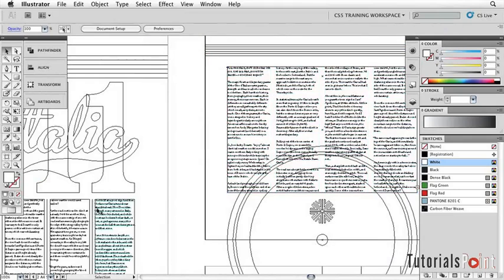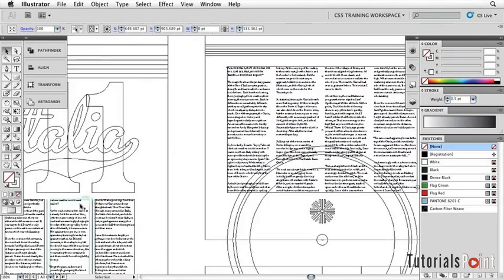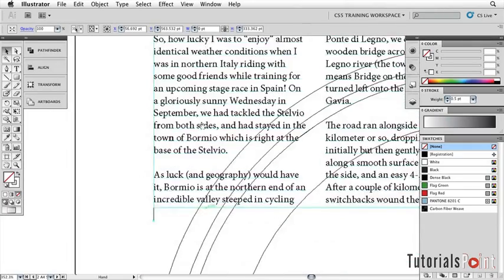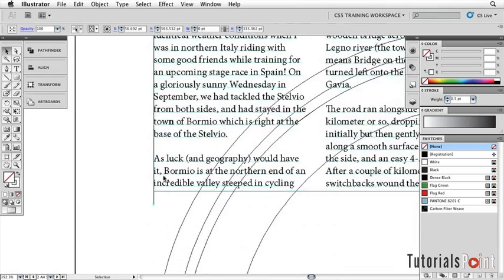So what we're going to do is come down here and take one of the guides that's on the A3. I'm simply going to copy it, or in fact we could just hold down our Option key and drag a copy over here onto our A4 page. I'm going to zoom in a little way and make sure that we align this to the top left hand side of our frame. The reason I'm doing that is I just want to make sure that we can snap it to the same height as everything else.